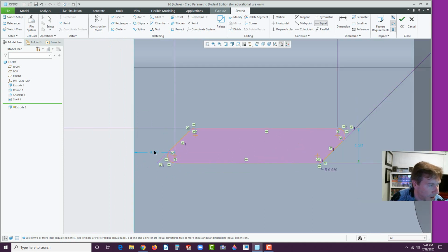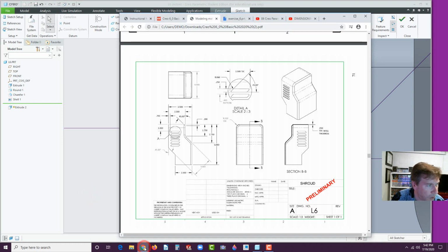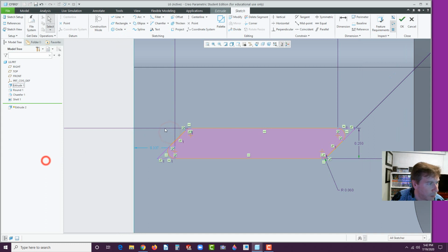Okay, now it lost our locator right there, and the height became weak, so let's change that. Let's middle click a couple times. And it'll be 0.25. So sometimes when you add geometry like that, it's going to do some interesting things. And this one, we want to go off the virtual sharp. So let's see, that was supposed to be 0.25 right off that virtual sharp. So let's add that in. So from here to here, 0.25.